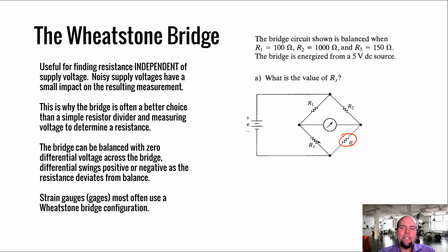So then this bridge is basically saying, at 25 degrees C, the voltage across these two terminals is going to be 0. But as that temperature goes above 25 or below 25, we'll actually start to produce a differential voltage. And if we start to produce a differential voltage, then that differential voltage will be slightly dependent on the accuracy of this V. But for the most part, if we're doing a sensor circuit, we're still substantially minimizing the impact of V on this signal. And a lot of times if we're doing a sensor, we really mostly care about this deviation from nominal.